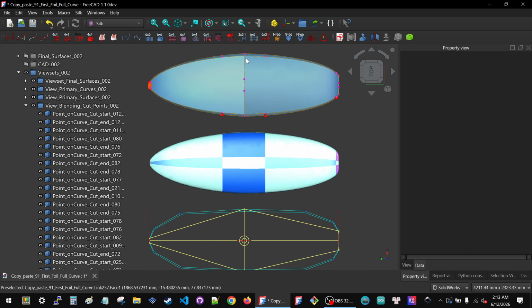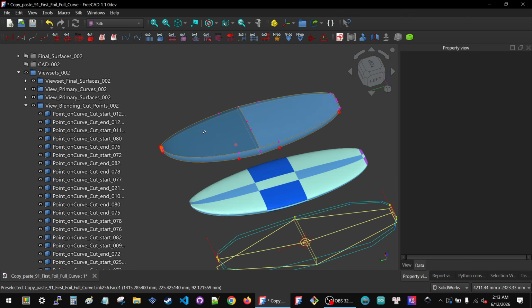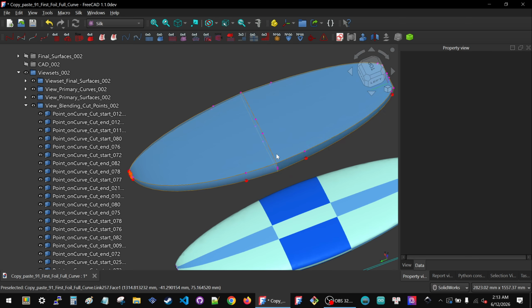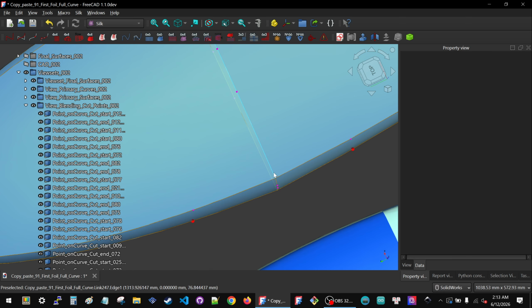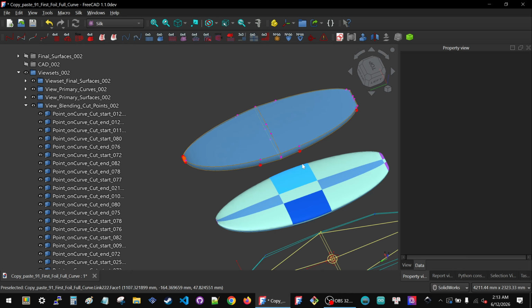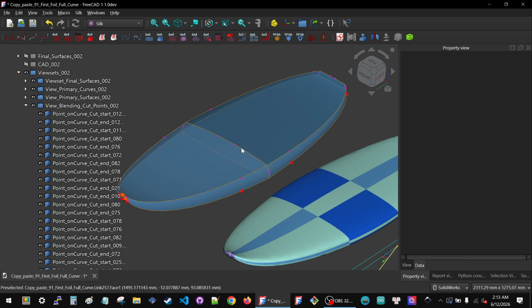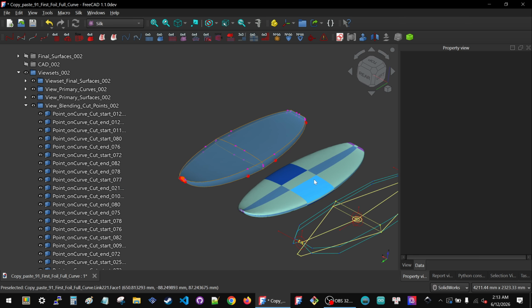You see now that I'm not using the blends to create curved surfaces. Not at all. I sculpt these curved surfaces directly, but the blend system allows me to not worry about having them be perfect to each other, which would be a waste of time. I use all the power these curves have to offer to create the overall shape. I allow these seams to not be perfect, and then I blend them.